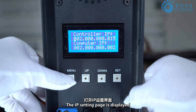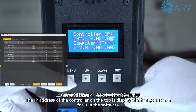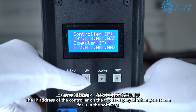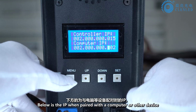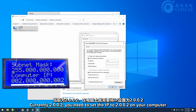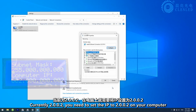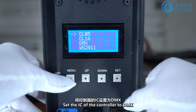The IP setting page is displayed. The IP address of the controller on the top is the one displayed when you search for it in the software. Below is the IP used when paired with a computer or other device. Currently it is 2.0.0.2, so you need to set the IP on your computer to 2.0.0.2. Set the IC of the controller to DMX.